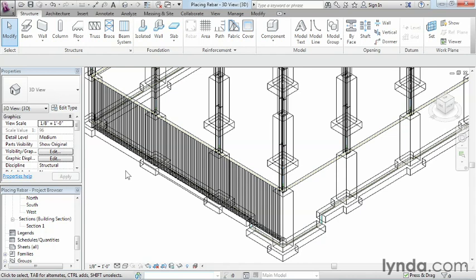That being said, whenever we place rebar, we always need to consider what its size is, what its shape is, and the location of placement. You pretty much always need to be inside of a section view as well in order to do it. But once we have the proper information set, as well as the proper cover depth so we know how far away from the outside edge of the wall it needs to be, we can easily drop the rebar into our design.